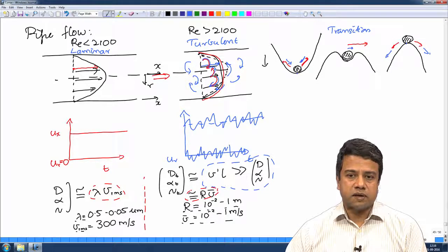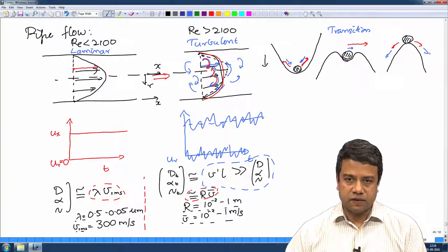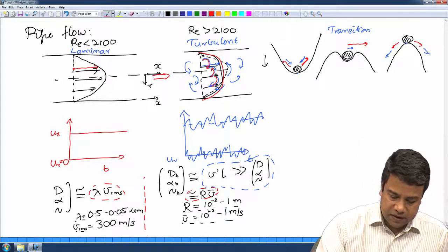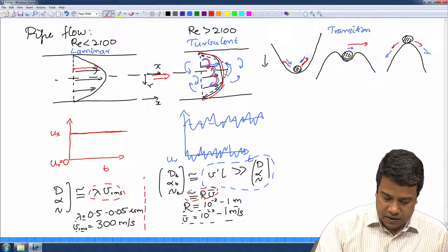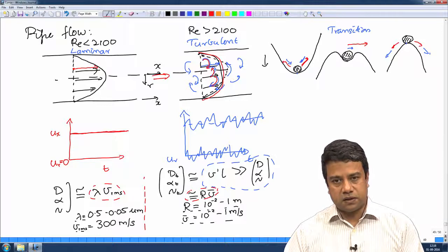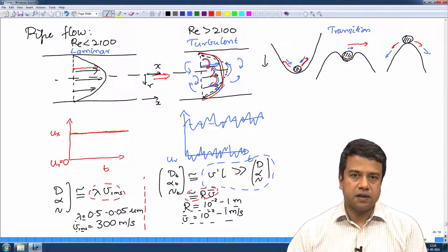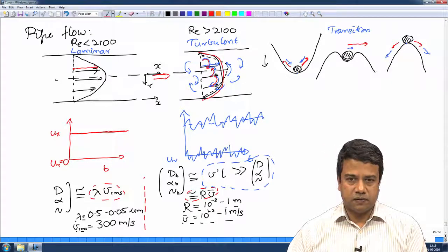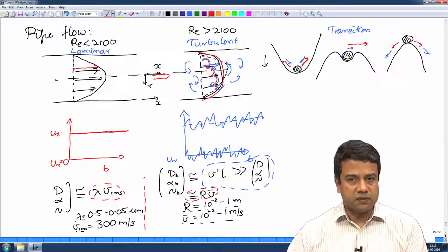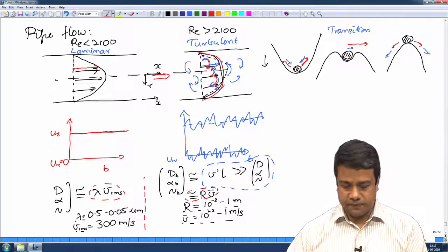The turbulent flow is not steady. There are velocity fluctuations at every location in all three directions. In a laminar flow, if I plot the velocity as a function of time, it will be only along the streamwise direction and it will be equal to a constant value. There is no cross stream velocity. And therefore, in a laminar flow, the flow is steady. The fluid fluctuating velocity is 0, even though there may be molecular fluctuating velocities. It is these molecular fluctuating velocities that give rise to diffusion.